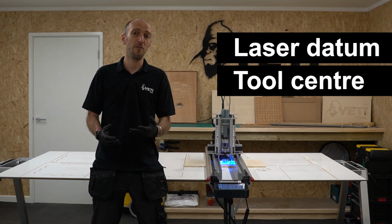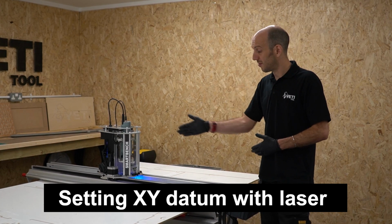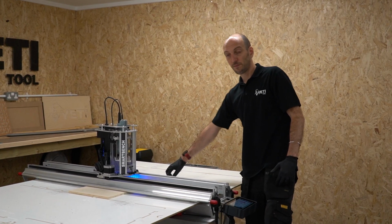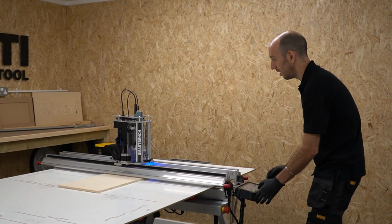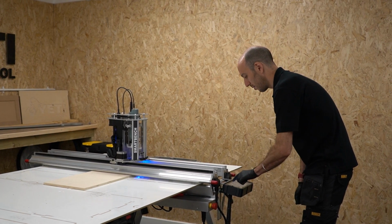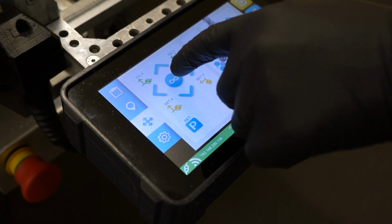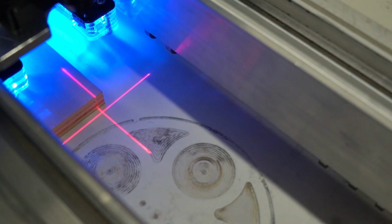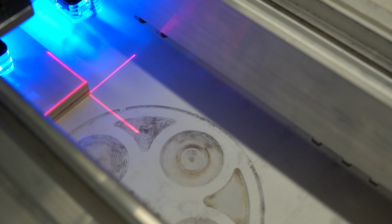So first of all, we'll cover using the laser datum. I'm going to move now the Z head such that the laser datum crosshair aligns perfectly with the bottom left corner of my stock. To do this, I'm just using the manual move buttons. I'm going quickly on the rabbit setting there just to get into an approximate location. Then I'll go to the turtle mode, which just slows it down a little bit. And I want to now move to 1mm increments to zone in on that corner. And then 0.1mm increments to fine tune it and get really good alignment.